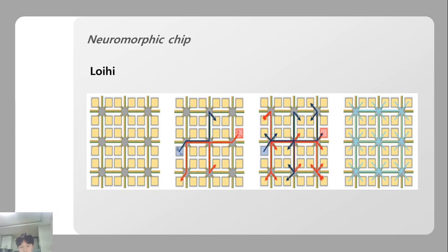Each square represents a core in the mesh containing multiple neurons. Then neurons in cores fire and generate spike messages. Spikes from all other neurons firing on time step t in cores are distributed to their destination cores. Finally, each core advances its algorithmic time step to t plus 1 as it handshakes with its neighbors through barrier synchronization messages.